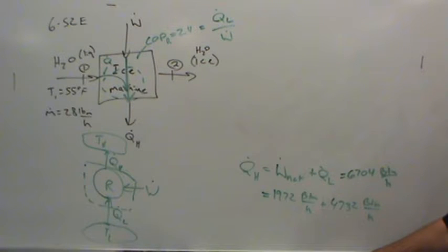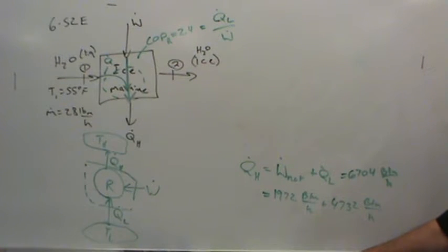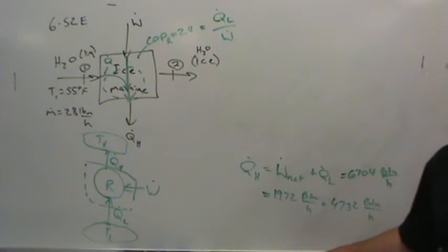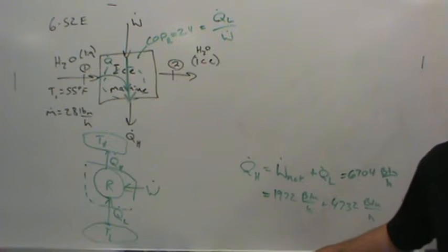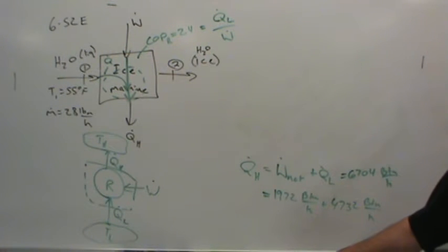So let that operate for 24 hours, so 24 times 18,000. That's how much energy you have to remove. Go ahead and calculate it if you would. I've never thought to calculate how much energy you have to pull out of literally 1 ton of water to get it to go from 32 degree liquid water to 32 degree solid ice. So what is 24 times 18,000, or 12,000?